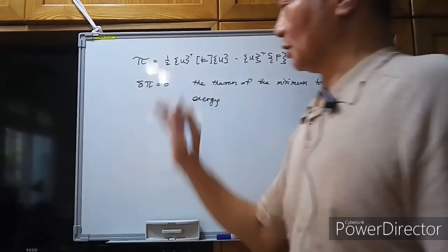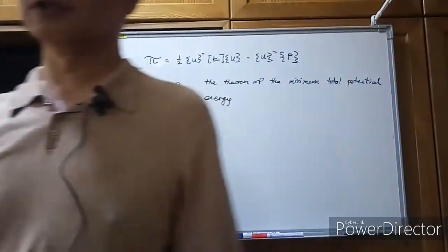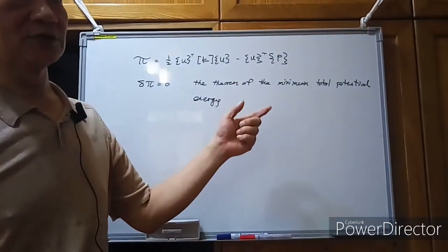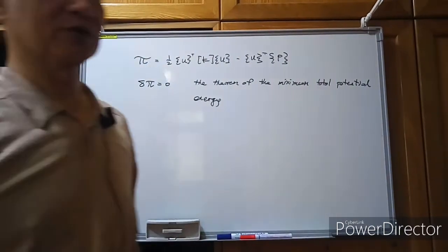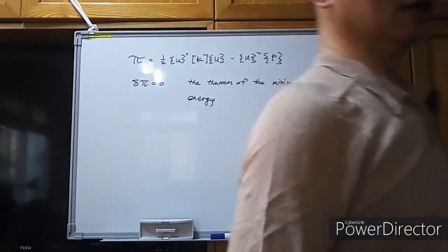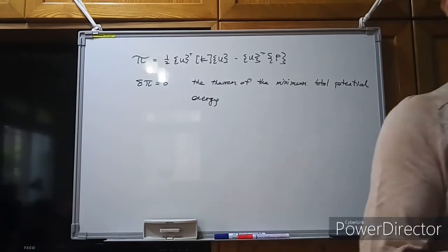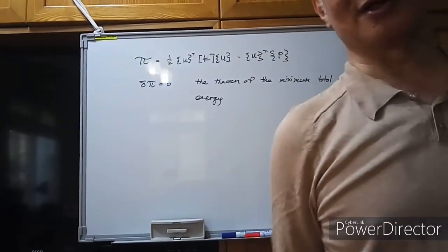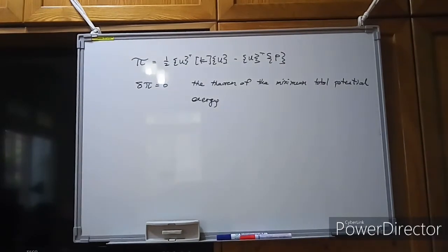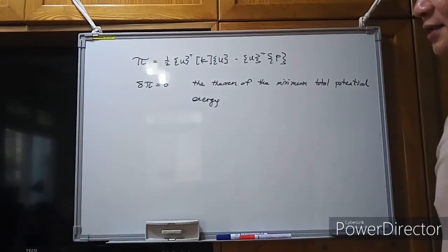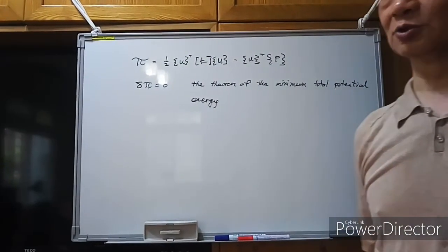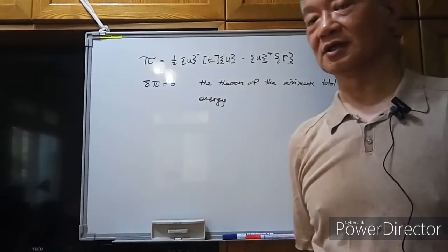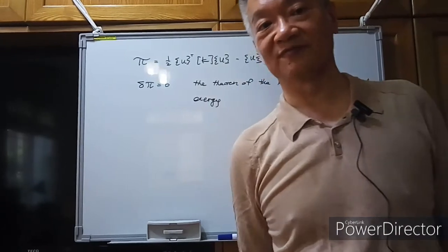Also remember this theorem, which is an alternative method to consider the equilibrium equations. The finite element method, most of the time, follows the displacement method. For the displacement method, at the beginning we need to assume a set of possible displacement functions.